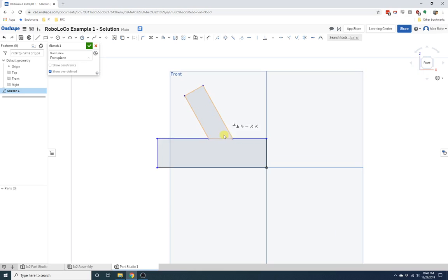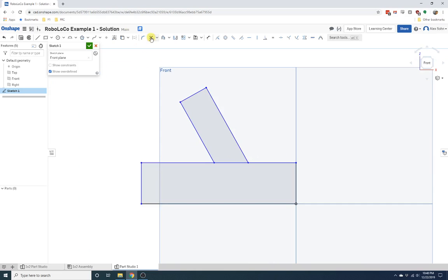I don't think in Onshape you really have to have enclosed spaces, but I like things to be clean, so I don't like lines going across. But that's just me. In some other programs like PTC Creo, which I'm used to, sometimes you have to get rid of those lines, otherwise it won't extrude correctly.